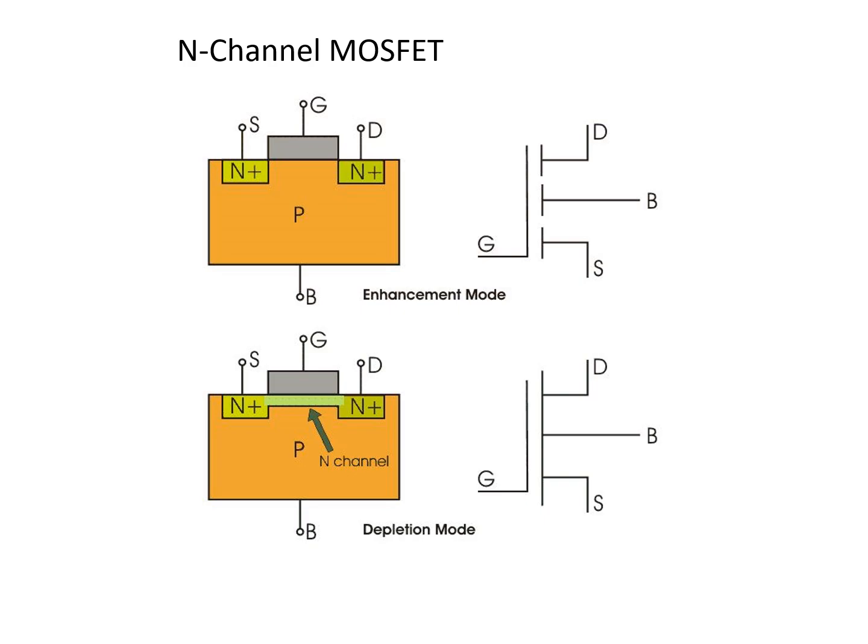Now, N-channel MOSFET. In N-channel MOSFET, the drain and the source are heavily doped with N region and the substrate is P-type. The current flows due to the flow of negatively charged electrons, and that's why it's known as N-type channel. When we apply the positive gate voltage, the holes present beneath the oxide layer experience repulsive force and are pushed downwards into the bound negative charge which are associated with the acceptor atoms. The positive gate voltage also attracts electrons from the N source and drain region into the channel, and thus an electron-rich channel is formed.